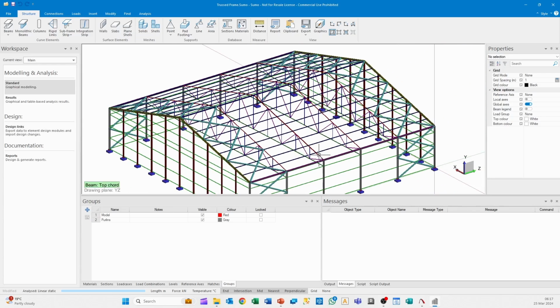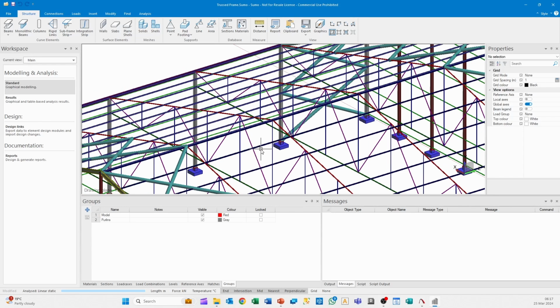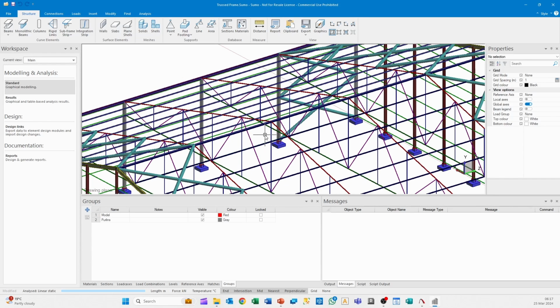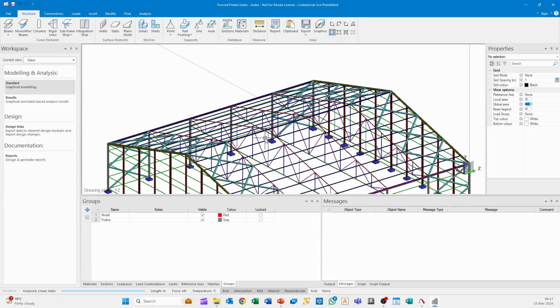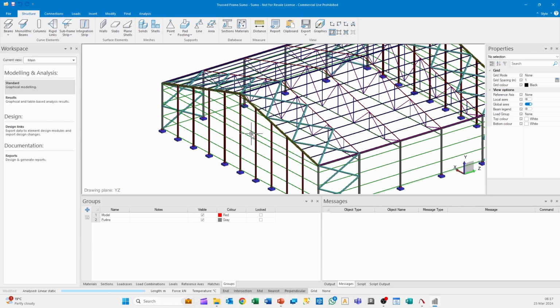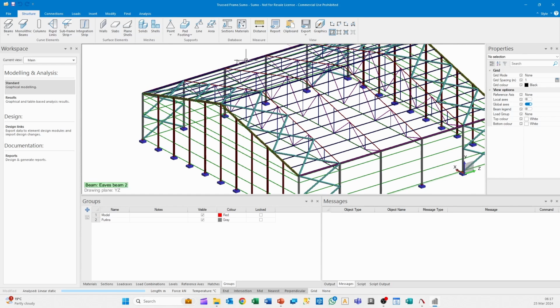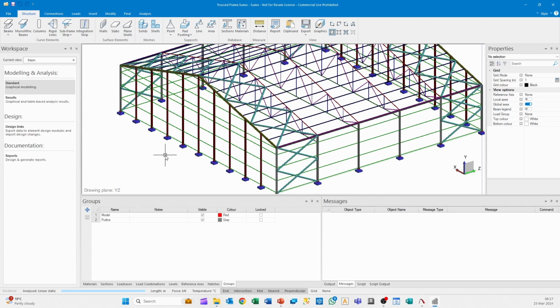So for those unfamiliar with design links, what they are is they basically export data, the analytical data, and the cross-sectional data of a group of elements or members to their respective design modules so that you don't manually have to carry over all of the design data. So that's, or rather analysis data. So that's your bending moments, your shear forces, etc.